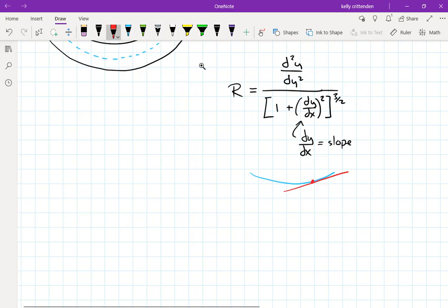And if I know that I want the slope of the tangent line to be pretty small, you know, it can have some deflection, but not a whole lot of deflection. In the real drawing, this is even exaggerated probably. And when I draw the slope there, it's pretty horizontal, right? It's a small slope. I don't want a whole lot of deflection in these beams.